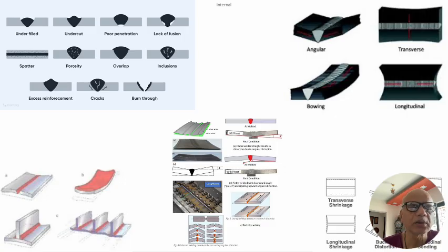The fourth defect, the right hand top, lack of fusion, is a defect which is sometimes difficult to spot with the naked eyes, because you see as if it is penetrated fully, so you assume that while it has penetrated, it has also fused on the side walls or the edge preparation which has been done on the two plates or the two jobs which are getting joined.